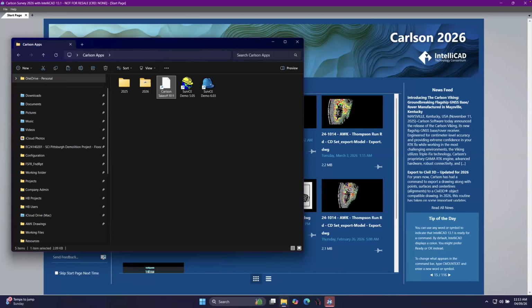And it can also output each of those different surfaces, not only the bottom of the excavation, the total subgrade, but each one of those individual layers you can generate as a surface. So you can check to make sure your layer thicknesses are correct as you go on. So a lot of flexibility all over the place. And that's one thing you're going to find out about the Carlson software, the fact that it's running inside a CAD program.